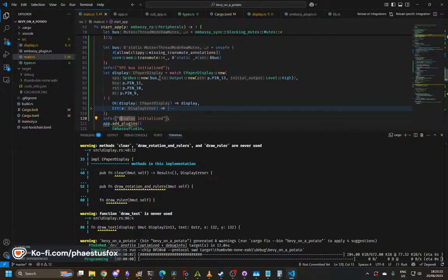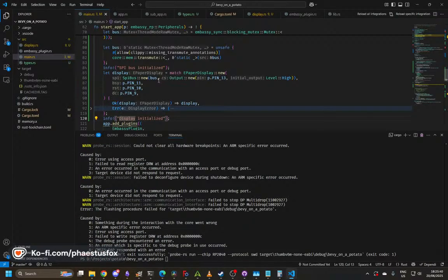That probably means that something's wired wrong, or something's not making continuity. Because it means it's probably never finishing its initialization. It's never calling init properly. So now we have to pop our multimeter out and connect our wires together. It's not going to like that, because I just unplugged the power to the thing, because I need to be able to get my probe. So I should be able to use my multimeter now.